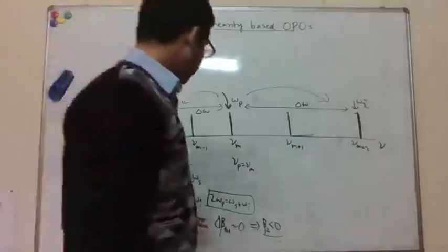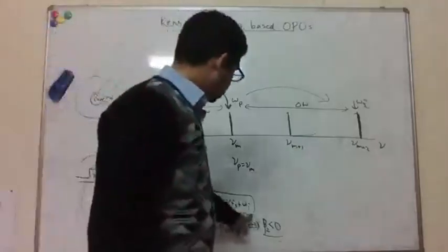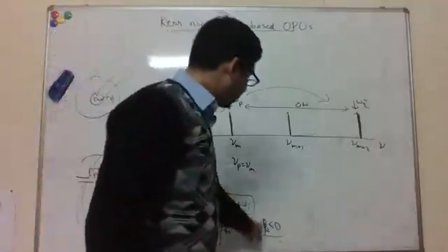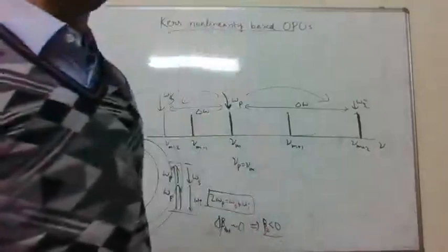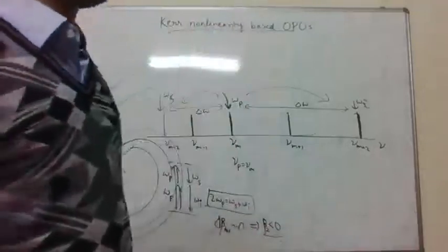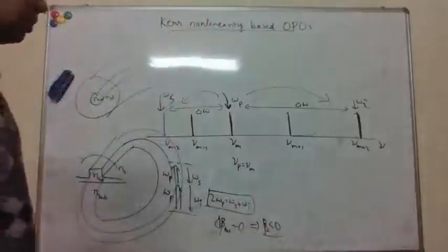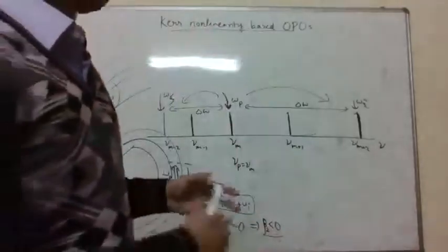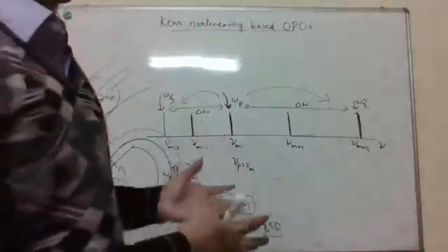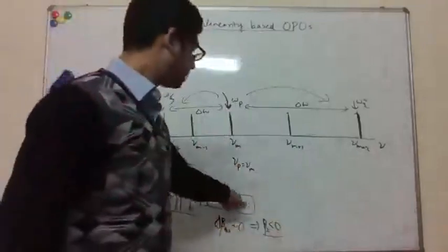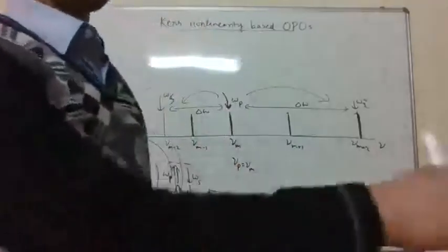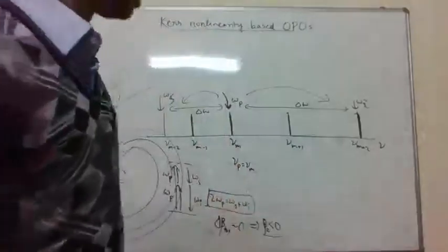A clue is, if you go back to our four-wave mixing, the reason we wanted this anomalous dispersion was because we were getting nonlinear phase shifts, the gamma p terms, and we finally wanted the usual delta beta: 2 beta p minus beta s minus beta i should be equal to 2 gamma p, which is the nonlinear phase.